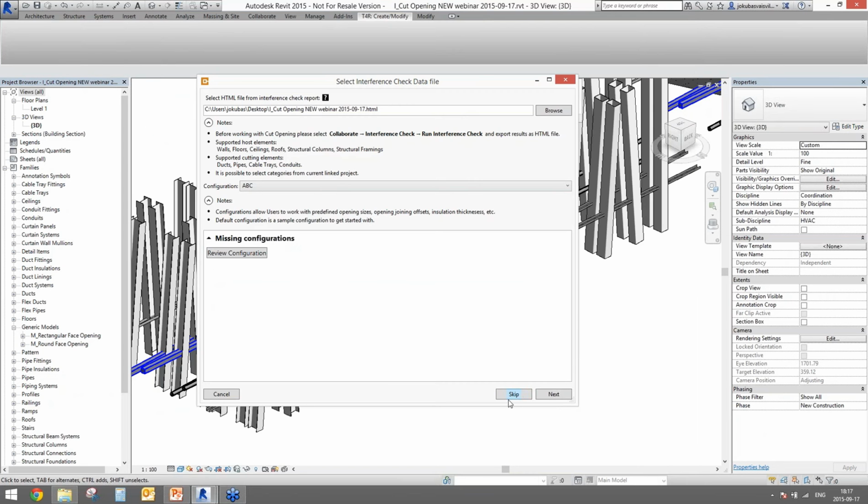After this, I will close, and I have 2 different possibilities. I can go to the next button that will allow me to insert only the not excluded elements. So if we do not add some of these and we use the next button, it will never insert the openings for these elements that still do not have configuration.